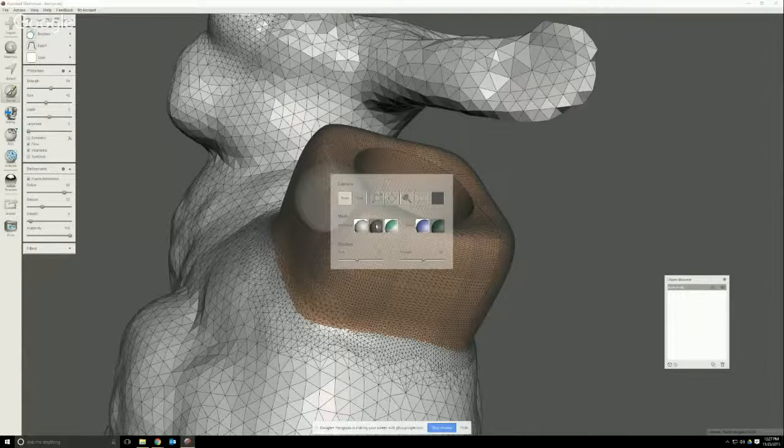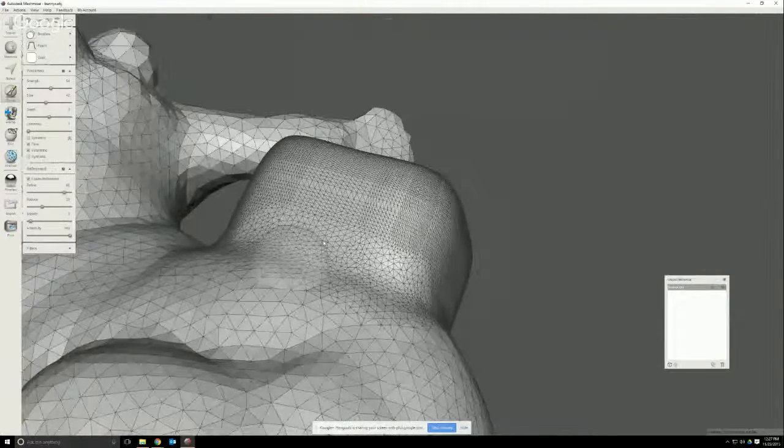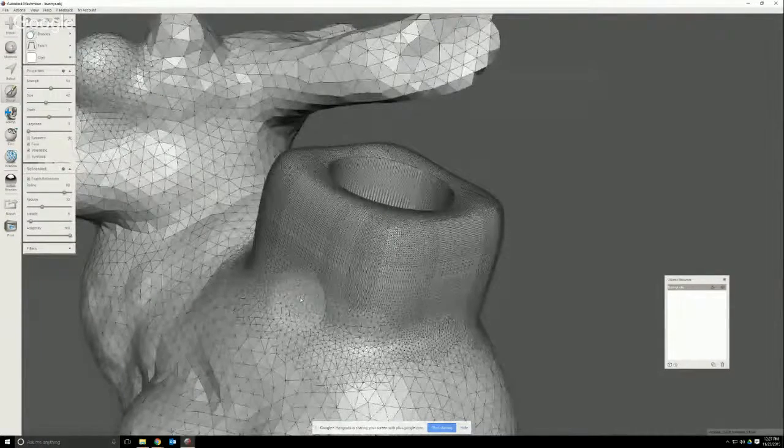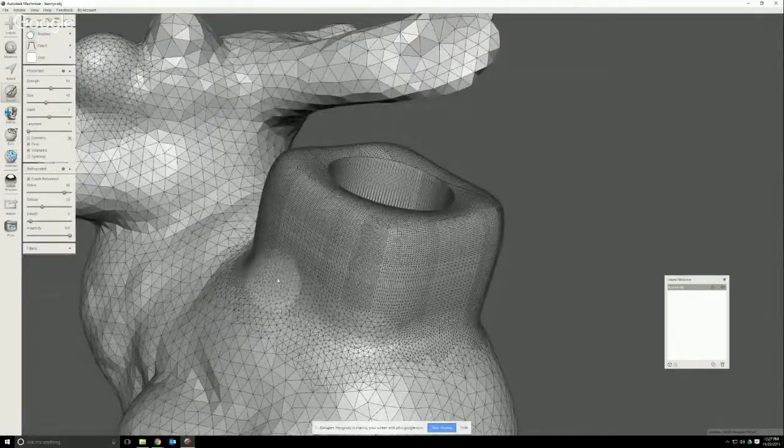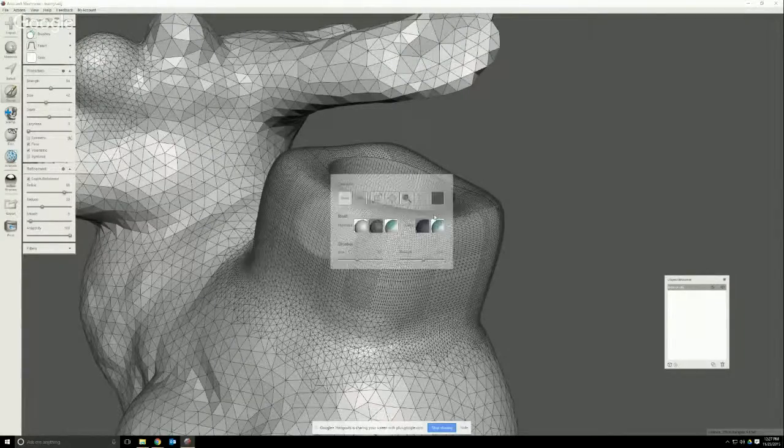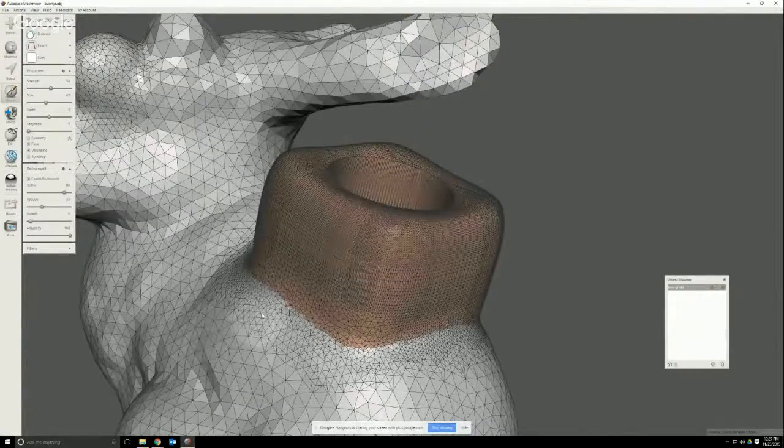I'm looking at the mesh normals, and this is the face group. This one is not enabled because it is still light colored. If I clicked on this, my color would disappear because now I'm looking at the actual color that would be assigned to the vertex groups for 3D printing and color. But I really don't want that when I'm working inside of Meshmixer. So I'm going to hold down the space button, make this one dark, and the face group is there.